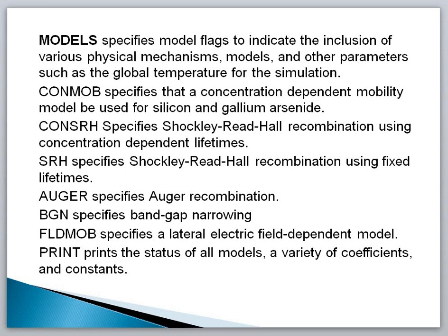CONSRH specifies Shockley-Read-Hall recombination using concentration dependent lifetime. SRH specifies Shockley-Read-Hall recombination using fixed lifetimes. AUGER specifies Auger recombination. BGN specifies band gap narrowing. FLDMOB specifies a lateral electric field dependent model. PRINT prints the status of all models, a variety of coefficients and constants. For detailed study of these models, you can go to the Atlas manual.